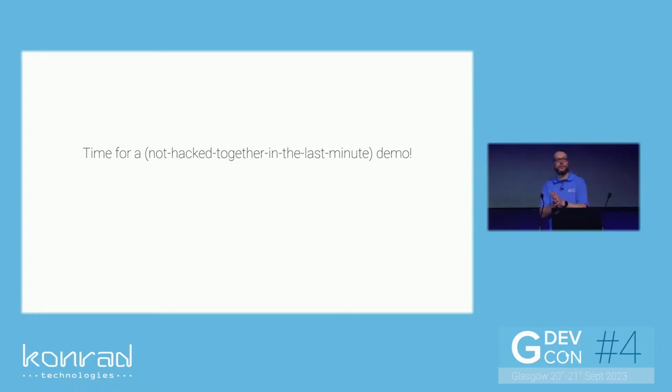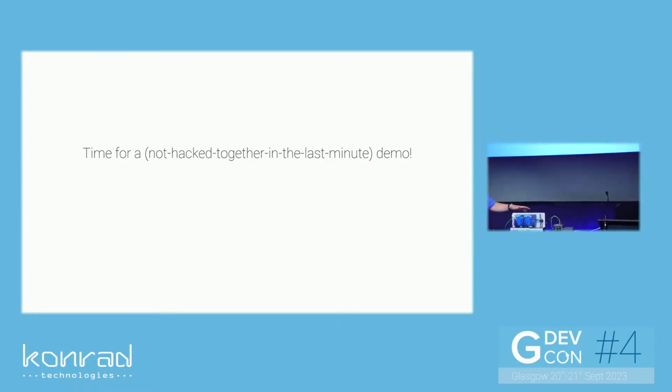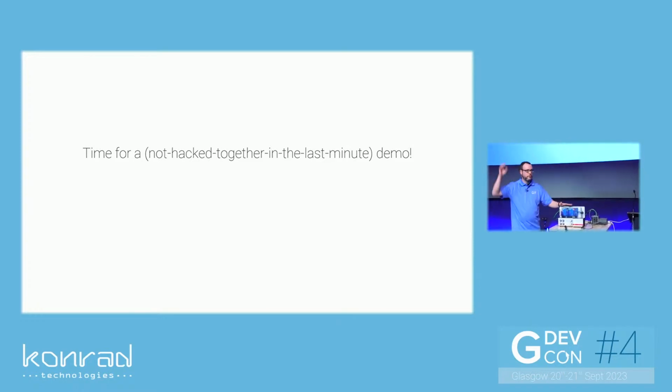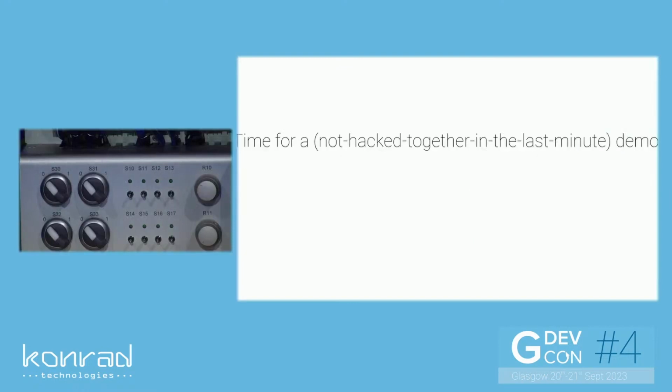So I wanted to show you, because I really like the way EtherCAT is implemented, I wanted to quickly show you this. What I've got here is a CompactRIO, no hardware in it, there are no modules, and this is a borrowed EtherCAT slave from our backers upstairs. They very kindly loaned this to me. I've got an EtherCAT cable, which is a network cable, connected to the EtherCAT port on this CompactRIO. If you're not familiar, on most CompactRIOs, you're allowed to turn the second network port into an EtherCAT port. Most people have probably done that.